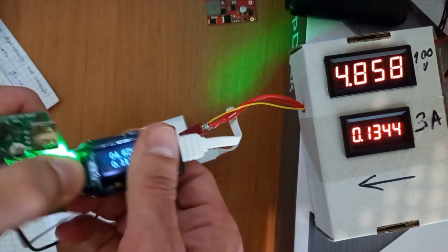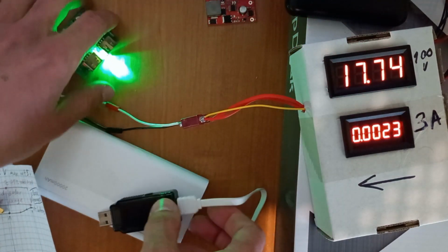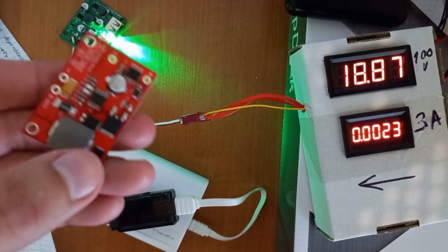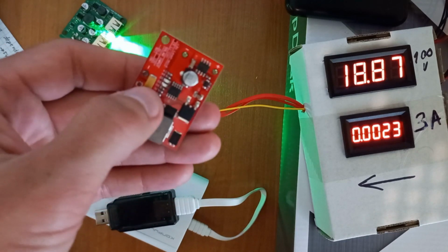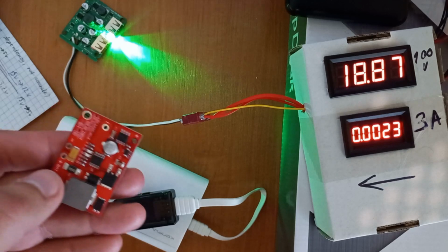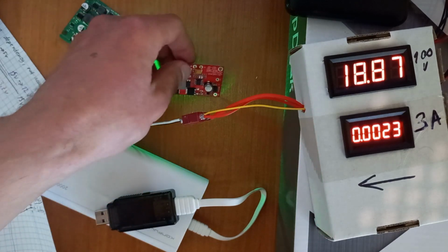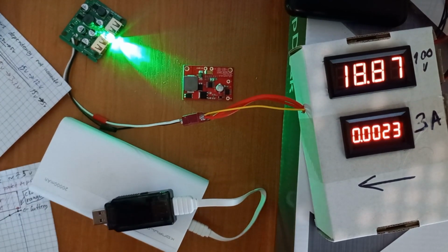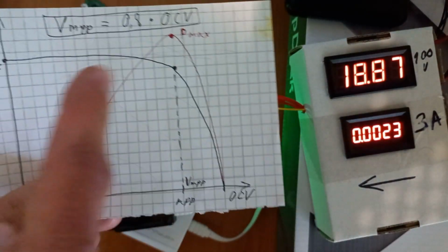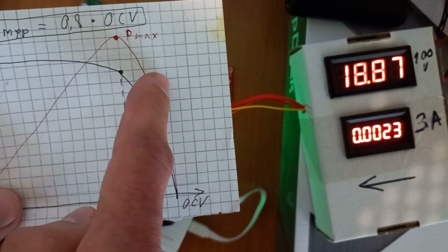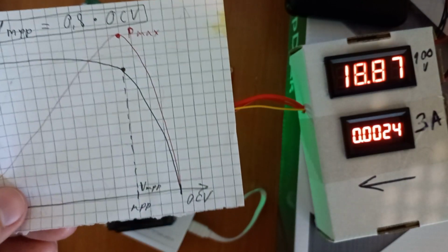Now about other alternatives. I've seen some devices reviewed on the internet that have an MPPT configured by a resistor. Actually, this one is based on such a chip, which configures tracking of a fixed input voltage. It's not an MPPT, they just claim it to be MPPT, which would work very badly. You either configure it lower for lower voltage and lose much, or you configure it for high voltage and can lose much more.